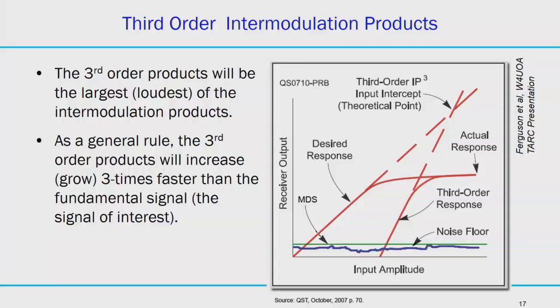For all these measurements, we don't take the absolute noise. We look at what our interested bandwidth is. Are we designing a gigabit transceiver or a 100 meg receiver? If 100 meg is our bandwidth, then we divide the noise by the 100 megahertz and find out where the noise floor is. That's the noise floor per hertz of bandwidth. That is the only way we can measure, and then everything is measured as power per hertz of bandwidth, so everything looks like the same measurement.